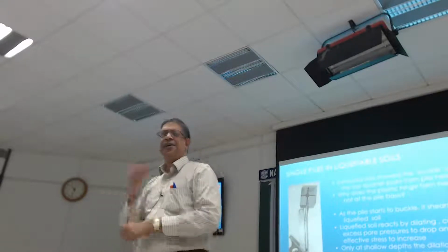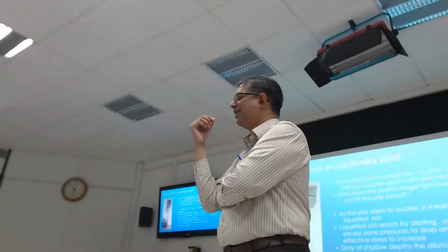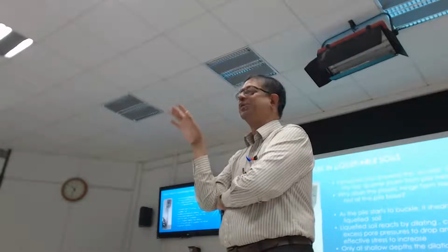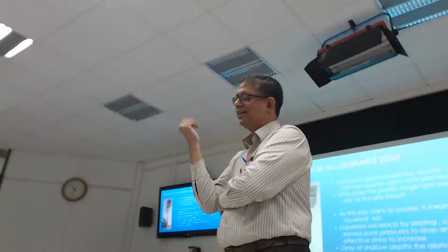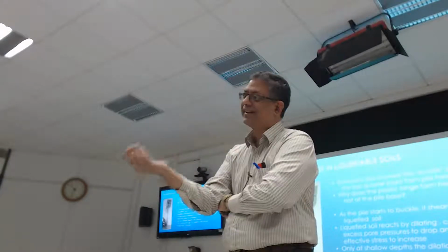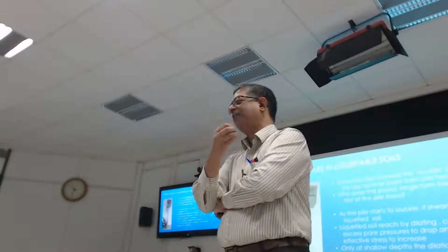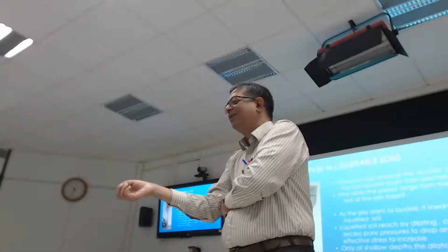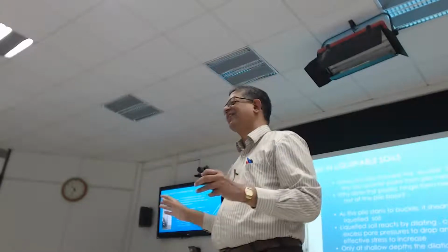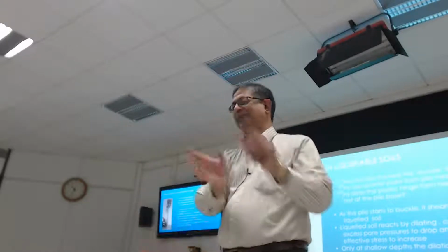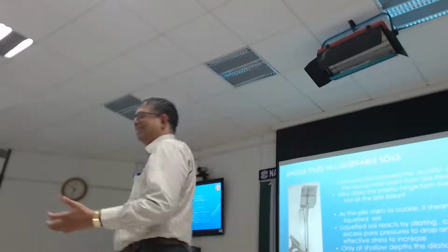I attended an IGC conference in Allahabad after that, and there was some person, I forget his name, good job, otherwise I'll just raise my blood pressure. He was trying to tell us that you can get the signal back from a saturated measurement record from the seismograph. And I said, there's no way in the world you can do that. If you saturated your signal, you lost it. There's nothing you can do. Go set your gains properly for the next earthquake and wait for the next 25 years.